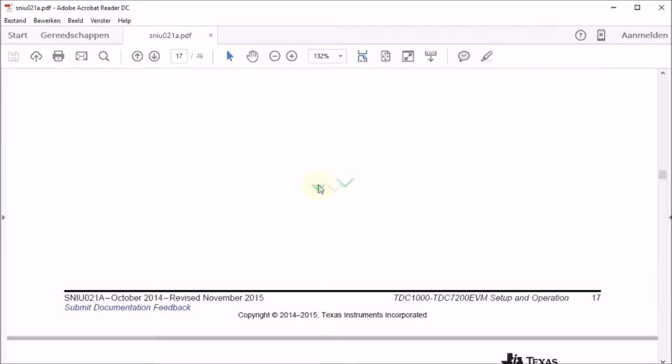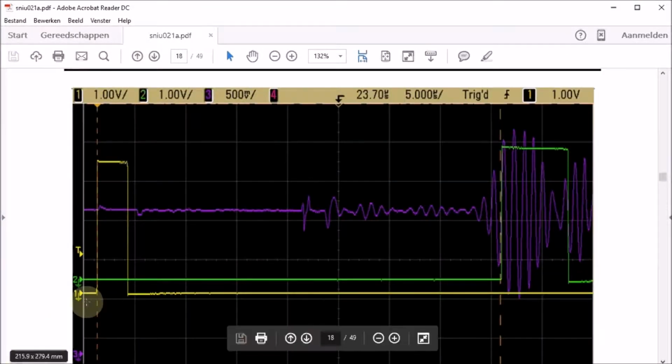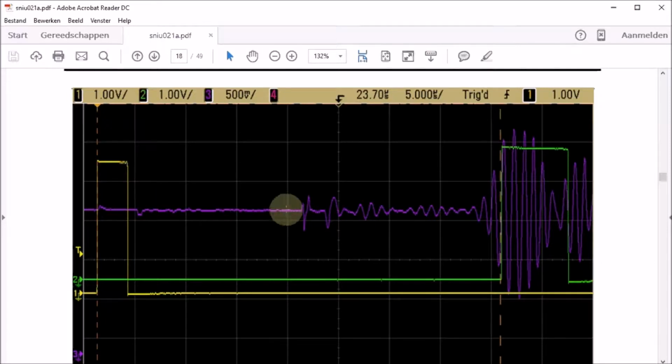The signal that we want to see on the screen is the start pulse here, the moment that the driver is going to excite the piezo sensor. We want to see the stop signal, and we want to measure the difference between the start and the stop here, and we also want to see what analog signal is going to the piezo sensor and what is coming back. So I'm going to visualize those 3 signals on a 2-channel scope.